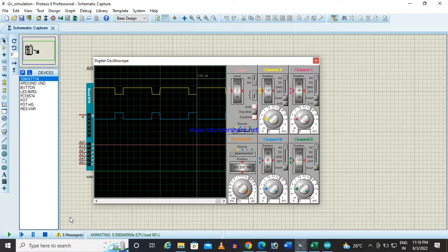This concept is very useful to generate PWM signals for a multilevel inverter, where the carrier frequencies do not go from 0 to a certain value but change in between, and are compared with your modulating sinusoidal signal.